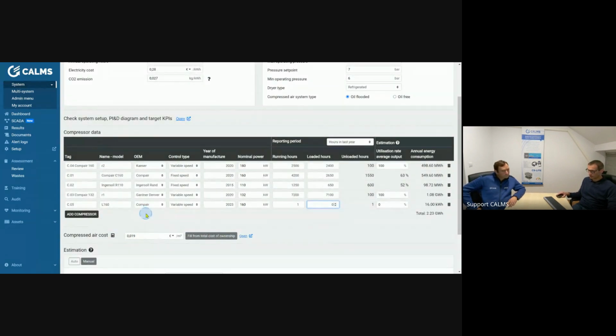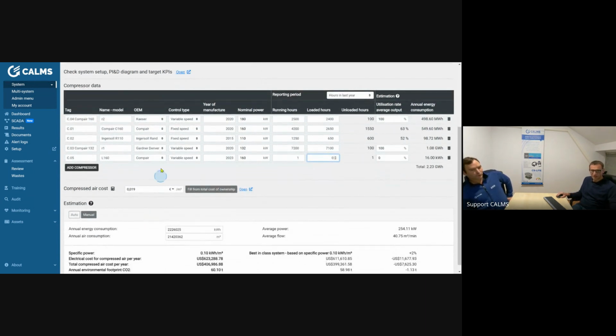And then in the end, what I would also like to do is the performance test of the compressor, so that I can check the actual performance of this compressor compared to the data sheet that your supplier provided to you, just to double check if there is some difference. We will find the culprit that is not giving the pressure. Exactly, that's what we want to do. We would like to find out which compressor is not performing well. Probably this is not the cause of the pressure drop, but we will find out. Better to have more information.